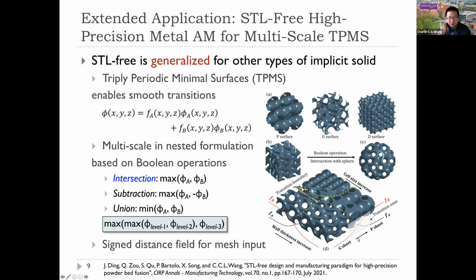And here is another extension of our algorithm. We further developed this method not only for lattice structures, which use only edges as skeletons, but we can also generalize this pipeline to STL-free slicing algorithms. So we're applying this STL-free high precision metal 3D printing to multiple-scale TPMS.